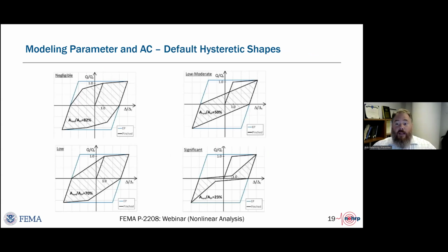The other thing that's really important in nonlinear response history analyses is making sure that your constitutive model behaves appropriately. And heretofore, ASCE 41 has been concentrated on creating a backbone curve that populates what is happening in quadrants 1 and 3 of the full hysteretic response of the components. But the standard says nothing about or gives no guidance other than to say match testing for what quadrants 2 and 4 should look like.